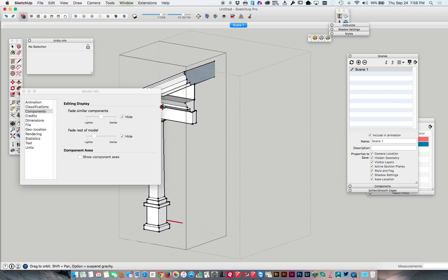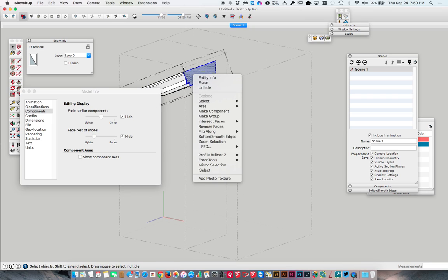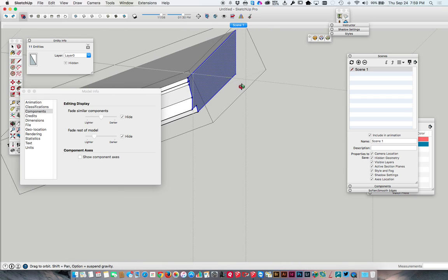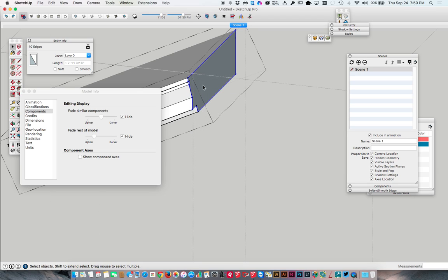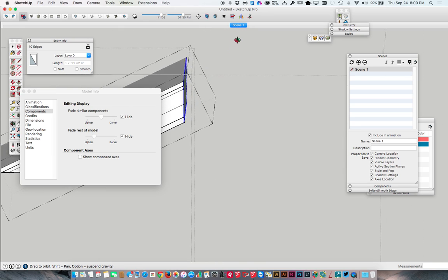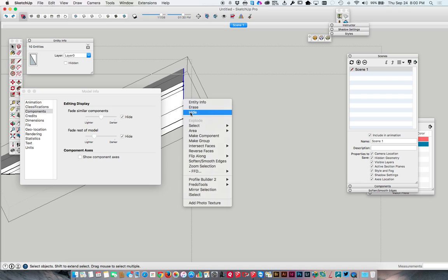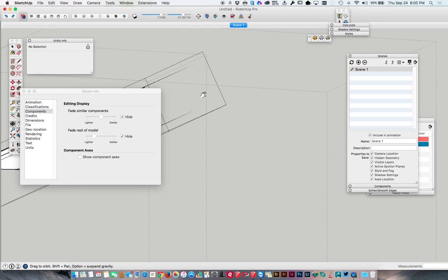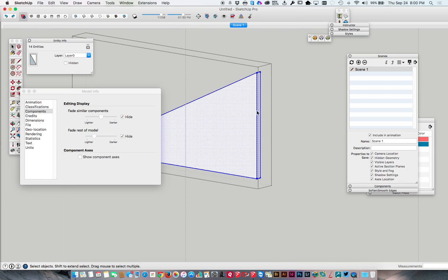So let's go in here and I'll select this stuff, and now this is saying unhide because there are some things that are already hidden. I could just unhide, but then it unhides that line. So let's undo that. Really what I want to do here is just line it up, select this geometry, and now I get hide. And so that's hidden. Come in here, select this geometry,